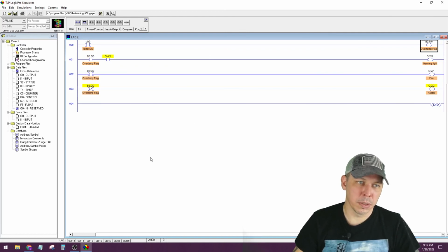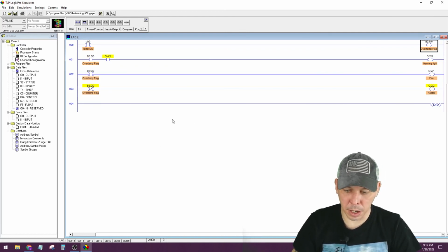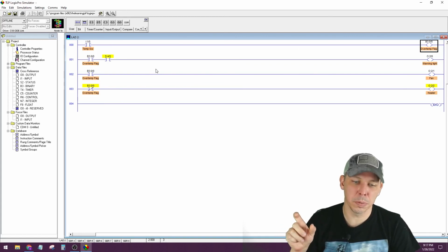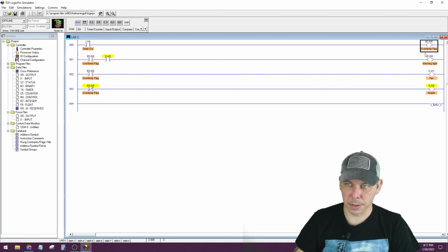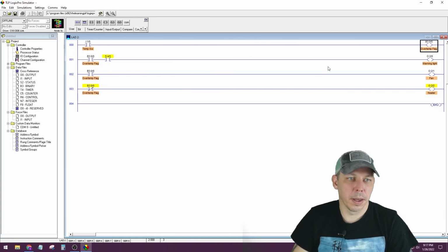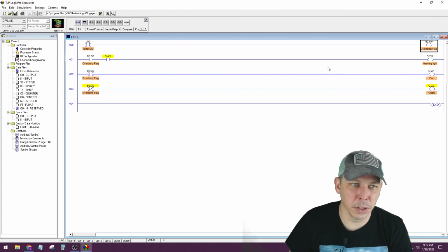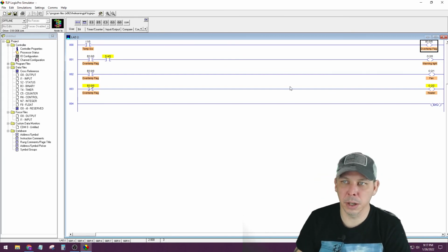And the way it's going to be used in the example for the project, project 4 for the door sensor, is that you're going to use this to kill the up and down motors, both of them. If there's a situation where the motor up is energized and you press the close button, if both of those are true, it's going to drop out the enable bit. So I have an enable bit over here. You'd have normally closed contacts, and when this goes true, those will open up, and those will kill the power to both motors. When you have it try to go the opposite direction, so it doesn't reverse immediately, it stops everything. There's a little bit more to it than that, but I'm going to have an example of that here too in a future video.